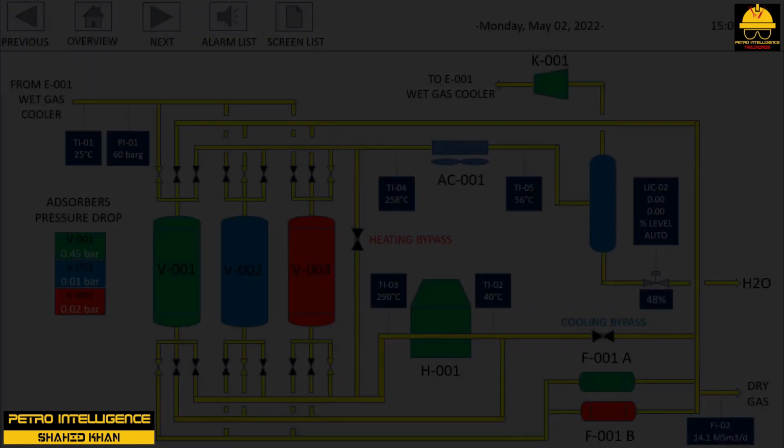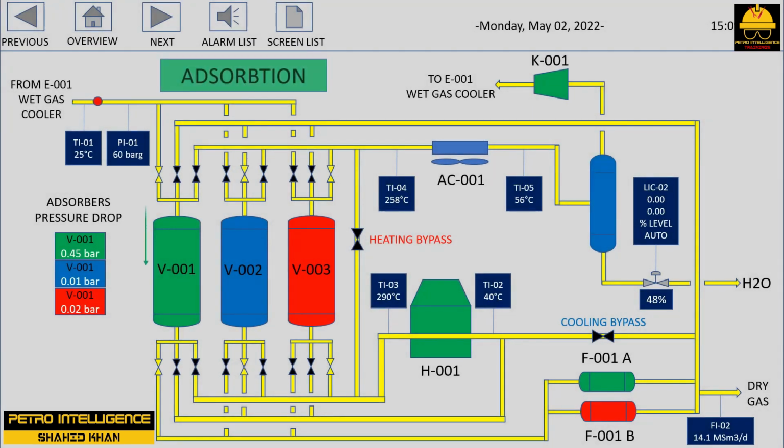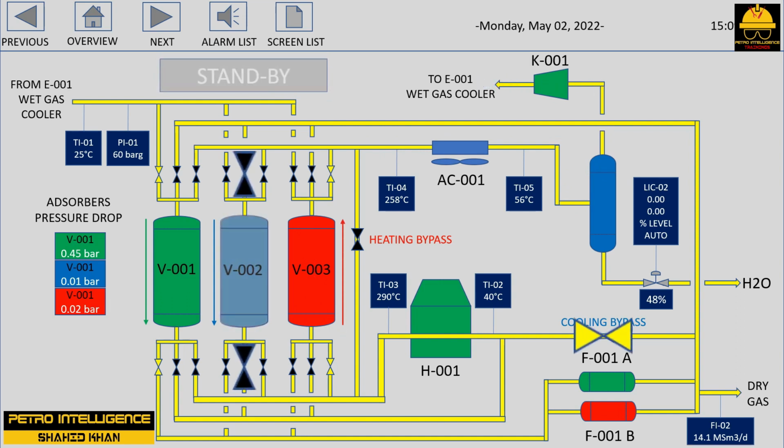Equipment. Equipment for adsorption operation is relatively simple. It consists primarily of a tank or vessel containing a bed of adsorbent, be it ion exchange resins, molecular sieve, or whatever. In most cases, the bed is fixed, that is, the bed is held in place while the process stream containing the impurities is passed through the bed. In a few cases, the beds are fluidized and are passed through the vessel countercurrently to the flow of the process stream. In such instances, the adsorbent particles are separated as they leave the vessel and are passed through a regeneration step. The regenerated particles are then recycled to the system.